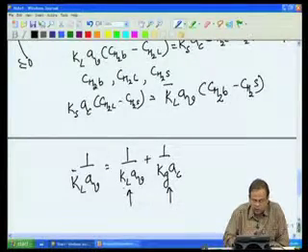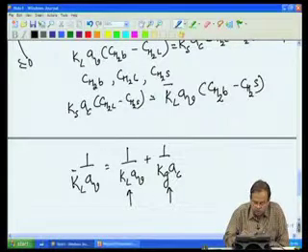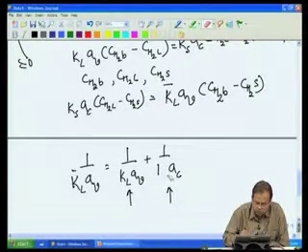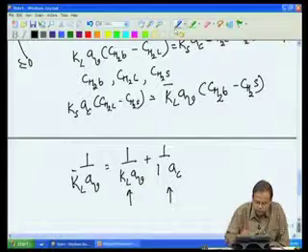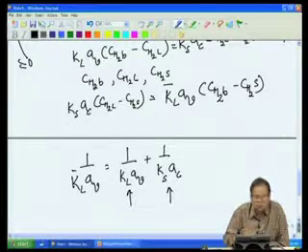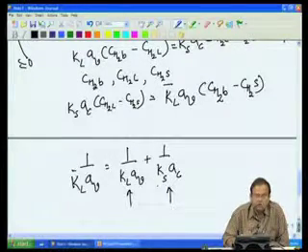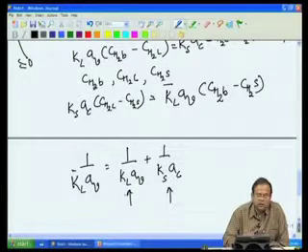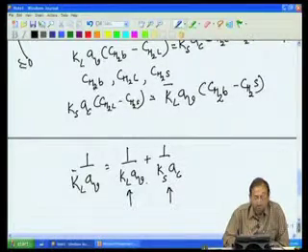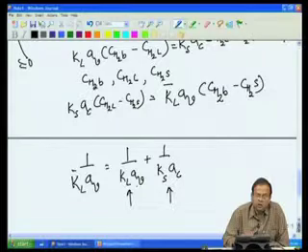Once again, what are KL and Ks? It should be Ks, not Kg. Ks is the mass transfer coefficient across the liquid-solid interface, KL is the mass transfer coefficient across the gas-liquid interface, and AV and AC are, AV is the area of the bubbles per unit volume of the liquid, AC is the area of the catalyst per unit volume of the liquid.